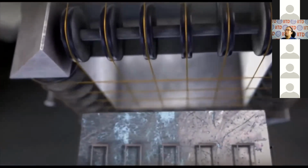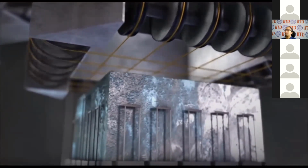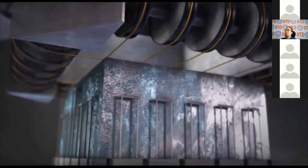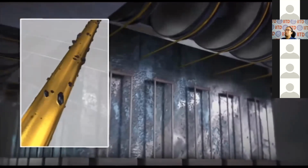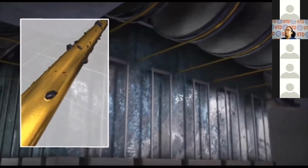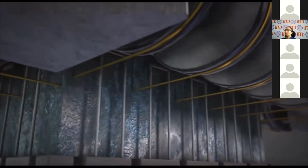A view inside the briquetter shows a cutting head with numerous deflection rollers, over which a special wire runs. The arrangement of the rollers ensures that the wire saw produces a matrix corresponding to the cross-section of the bricks. The cutting head slowly sinks downwards, causing the wire saw to cut through the silicon ingot. With rapid to and fro movements, the slurry, which consists of a mixture of silicon carbide and polyethylene glycol specially developed for the silicon cutting process, is kept in motion.